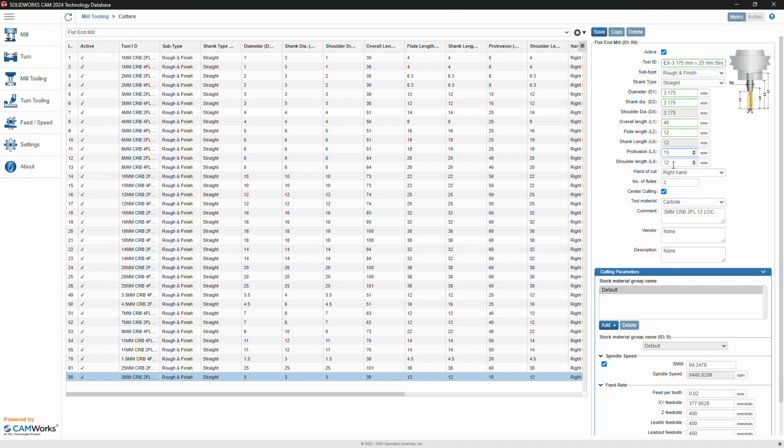And you'll see I'm getting an error message here because I have to adjust the shoulder length first. So the shoulder length and the protrusion length are both 33mm, and then I should be able to adjust my flute length because, of course, the flute can't be longer than the protrusion. So there we go. Now, I pulled these numbers off of our database on Makera.com, but you can also, of course, measure your tool to find these numbers, and SolidWorks CAM gives you this nice little graphic here that you can see. The protrusion would be what falls below the bit collar on your Carvera tool.